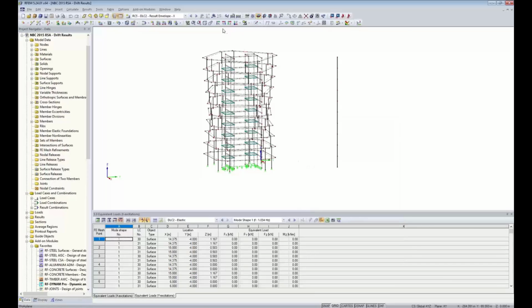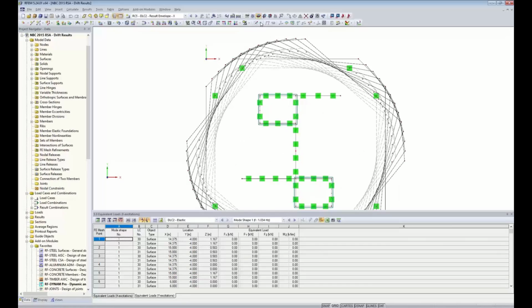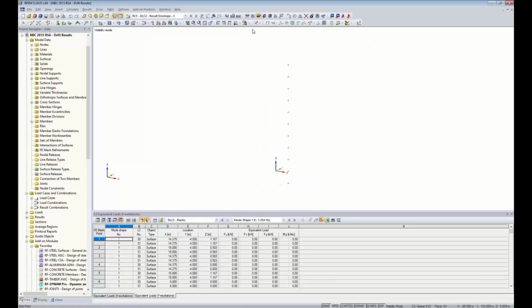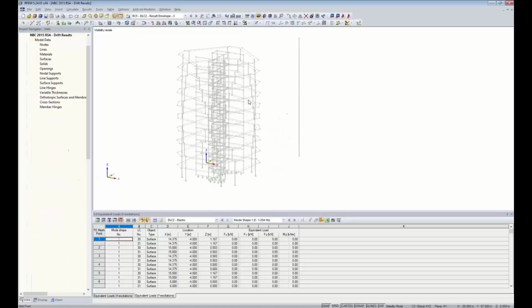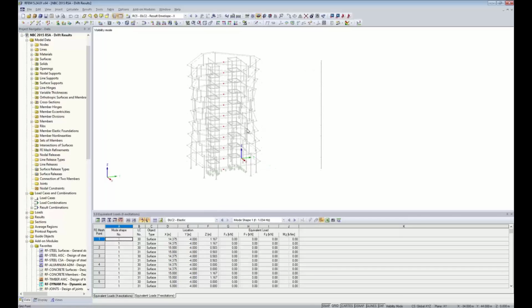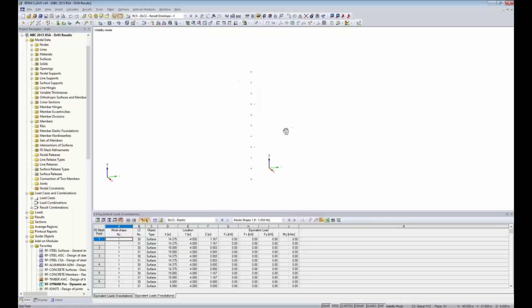And actually, let me show that once again. We'll create an isometric view and choose the visibility by the selected objects. Okay, so when I right click, previously this is what was shown with those hidden objects kind of shown in the background here, but just to give you better visibility, we can also turn those off by right clicking and turning off the visibility in the background.